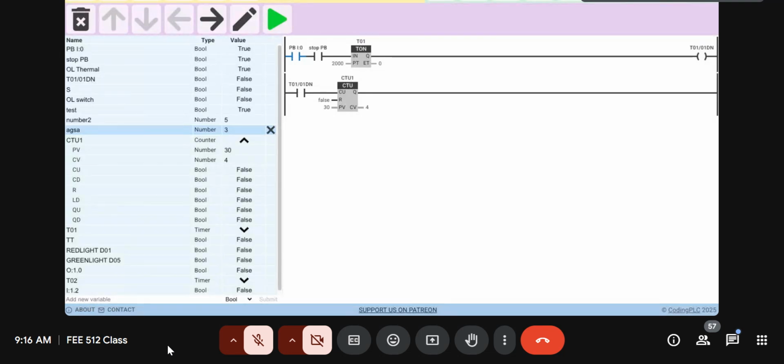If I simulate this exact same example with Siemens and with Rockwell or even with Omron, you might see slight variations in performance, because the timers and counters have slight variations from manufacturer to manufacturer. The variations are not so wide as to change the entire thing, but they are small, and it requires that you know about them. That's why they are accompanied by data sheets, so that you don't assume that all the PLCs will work exactly the same. The principle of operation will be the same, but there might be slight variations in how they work.